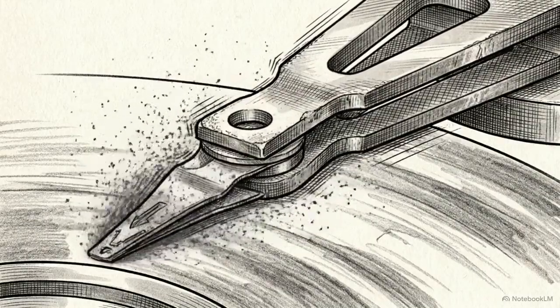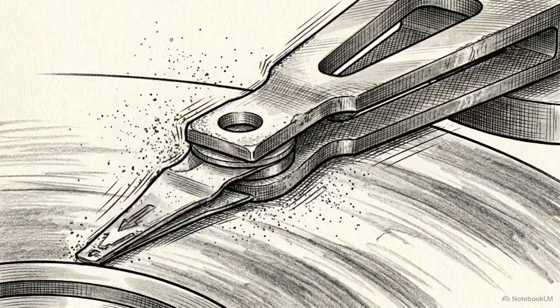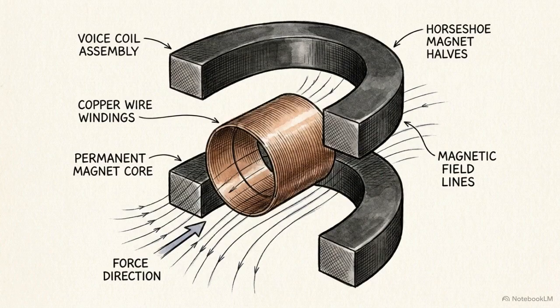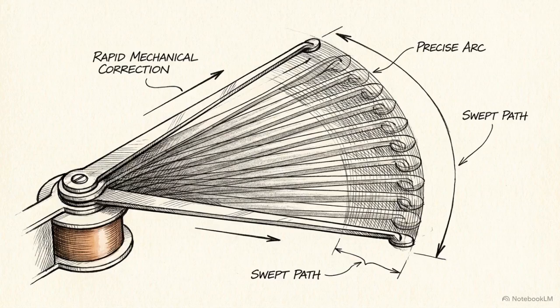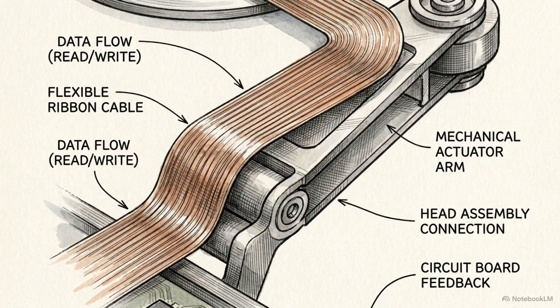Older drives relied on slow, noisy stepper motors that ticked across tracks mechanically. Modern designs use a voice coil mechanism, utilizing closed-loop servo feedback to monitor the signal amplitude and execute fast, sweeping corrections to the head position. Replacing physical friction with aerodynamic lift and precise servo motors allowed the read mechanics to successfully intercept the massively compressed, high-speed data streams generated by RLL encoding.